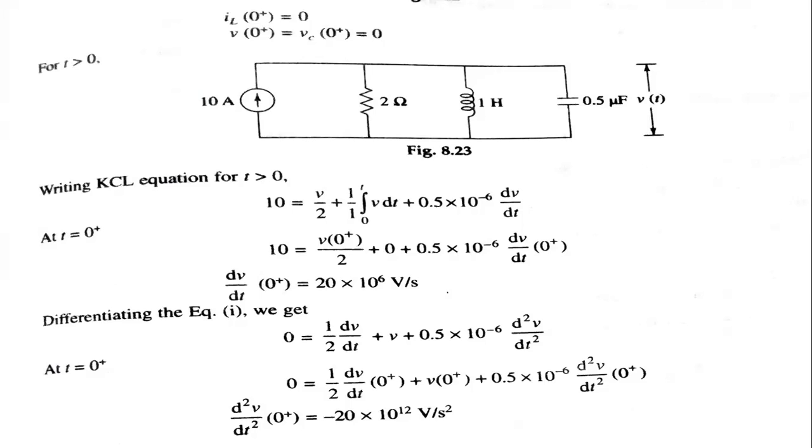Again at 0-, 0+, t > 0, apply the KCL and simplify the numerical using the KCL. In the KCL also, i = V/R. If simply R is there, then V/R. If R and L are there, V/R and V/L. If RC is there, then V/R and V/C. If all three are together, then with respect to the resistor, inductor and capacitor, write the voltage equation.